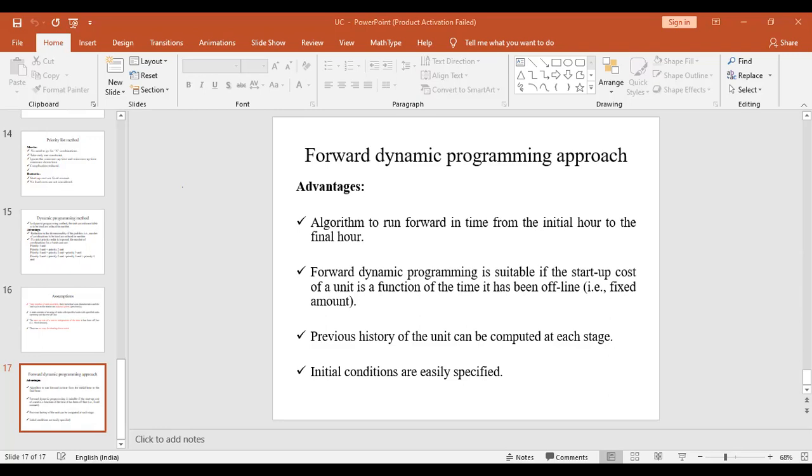The economic load dispatch is the online economic load dispatch problem, wherein the load is distributed among the generating units operating in parallel in the system in such a manner as to minimize the total cost of the system, supplying the load from minute to minute requirements of the system. The economic load dispatch problem is also a solution technique with a large number of load flow problems, choosing the most appropriate solution for finding the optimal result with the minimum cost of generation. These are the main aims behind economic load dispatch.